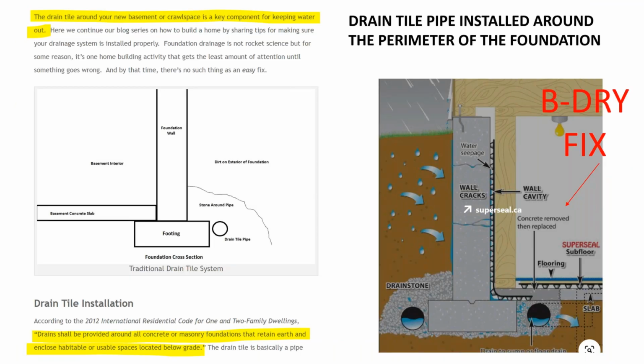The diagram on the left is explaining to you how the foundation is poured, and it talks about drain tile. Because the water sits below ground, the idea is to divert the water and control it, because the water, as we've talked about before, does more damage to a house than anything else. And so you try to control where that water is going to go.